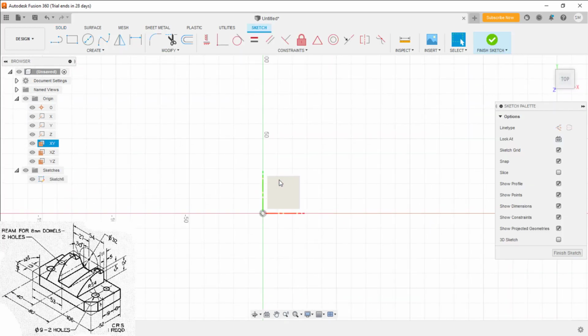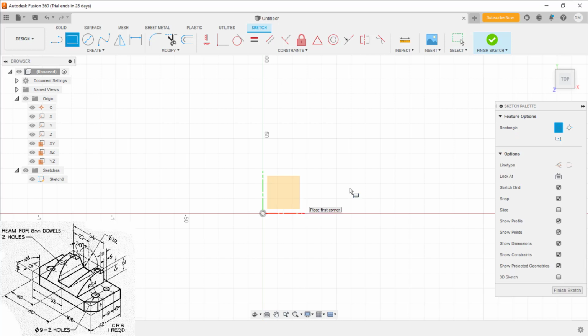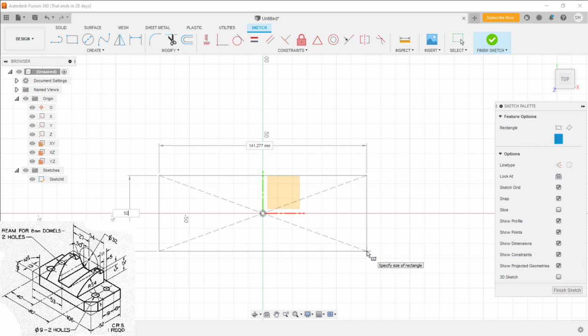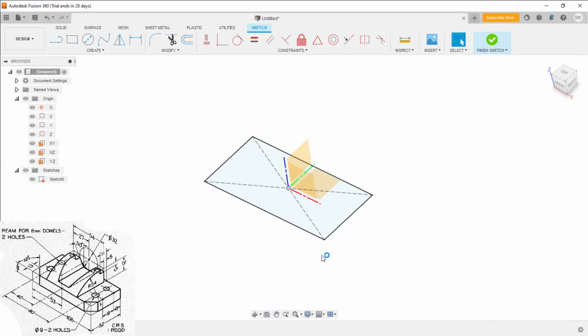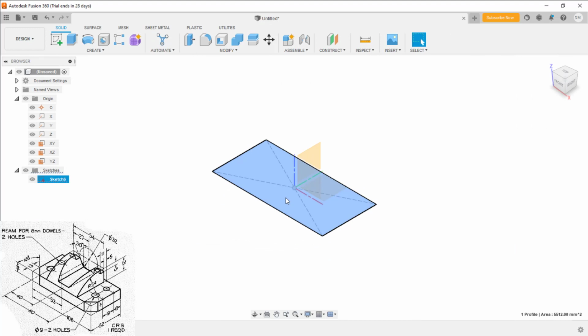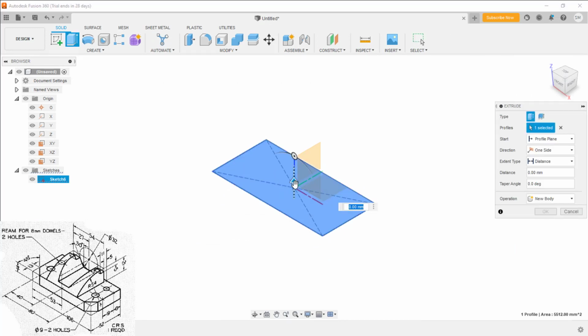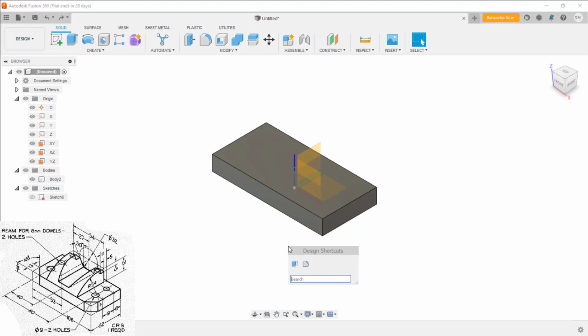You can start with the top plane, just right click and select it. Use the S key to switch to the shortcuts. Okay, center circle, here dimension to switch, tab. Okay, D is the shortcut to enter the dimension. So you can select the area, right click and use the push pull and enter the value here directly. It is mentioned here 14.